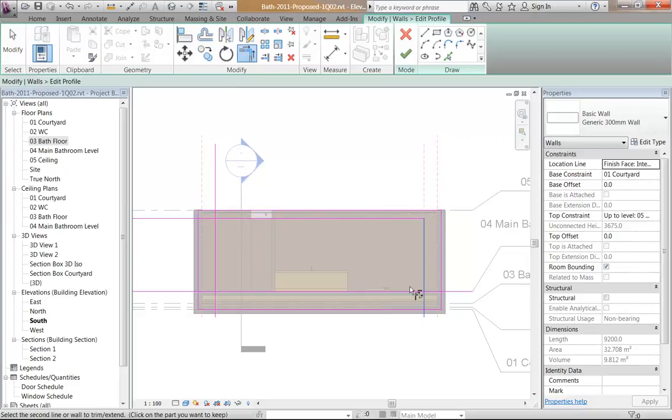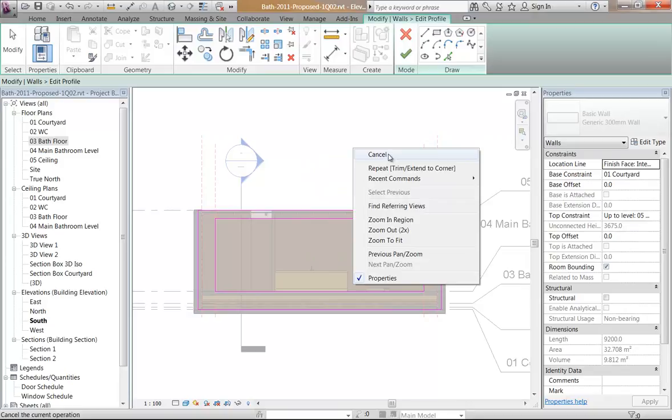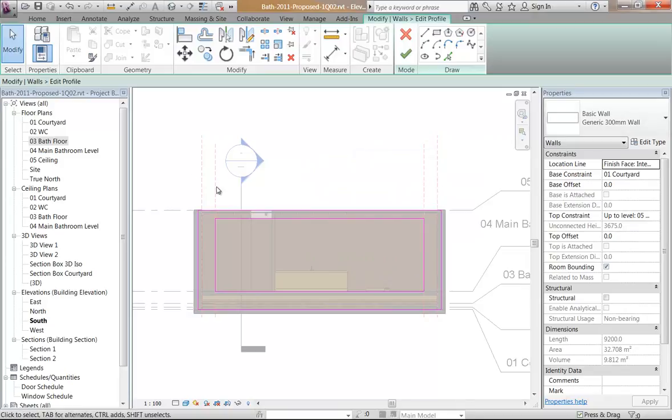So why don't you just make a rectangle? Oh, well, it's just easier to do it this way because I want it to be a certain distance from either side. And it's easier to measure that in plan, so I put those reference planes in the first place. And now I can just use pick lines to choose these two sides, and then also the bottom, it's easier to choose that from the level. Okay, so I'm just going to finish that.